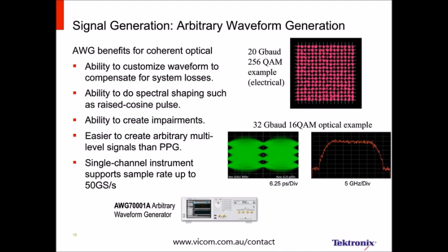So I think what we're seeing here in this ability to do the 256 QAM at 20 gigabaud is that because the products in question have a lot more bandwidth than that, once you apply that low pass filter, you actually get effectively a higher number of bits. So sometimes it's the point that when you look at, for example, digitizers, having more samples per second than you really need can turn out to be a big advantage, because then you can use low pass filtering to really improve your signal to noise ratio.